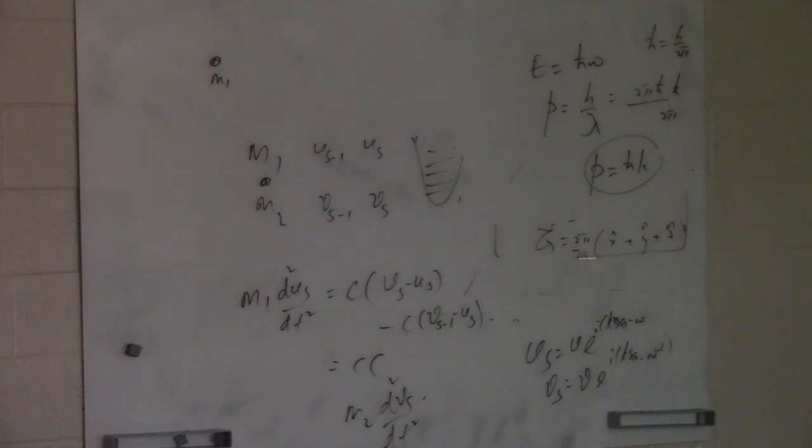If you provide some heat, that heat is carried by these phonons to the other end, right? So that means if there is no resistance for this flow, then you will have infinite conductivity, right? So that's what this says, right? When thermal energy propagates through a solid, they are carried by lattice waves, right? So that's what the phonons are.